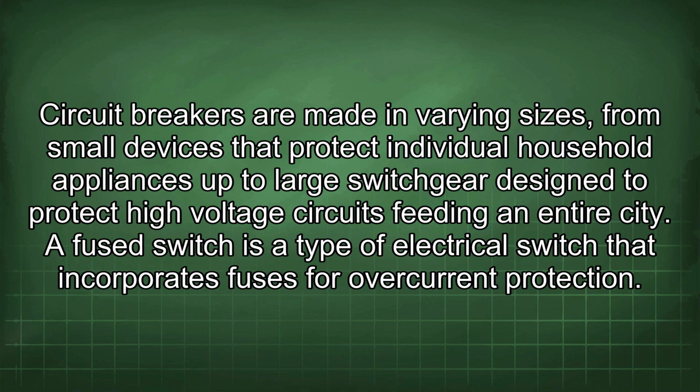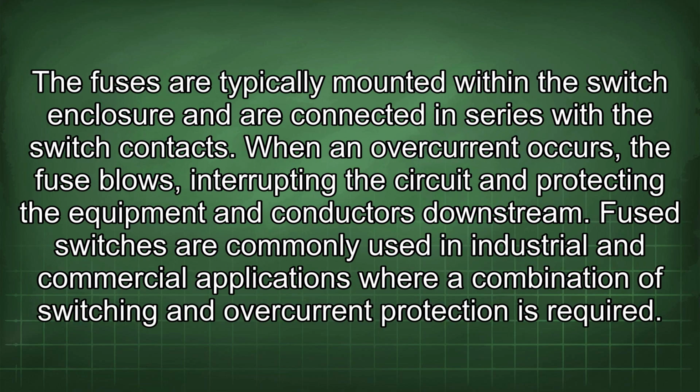A fuse switch is a type of electrical switch that incorporates fuses for overcurrent protection. The fuses are typically mounted within the switch enclosure and are connected in series with the switch contacts. When an overcurrent occurs, the fuse blows, interrupting the circuit and protecting the equipment and conductors downstream. Fuse switches are commonly used in industrial and commercial applications where a combination of switching and overcurrent protection is required.